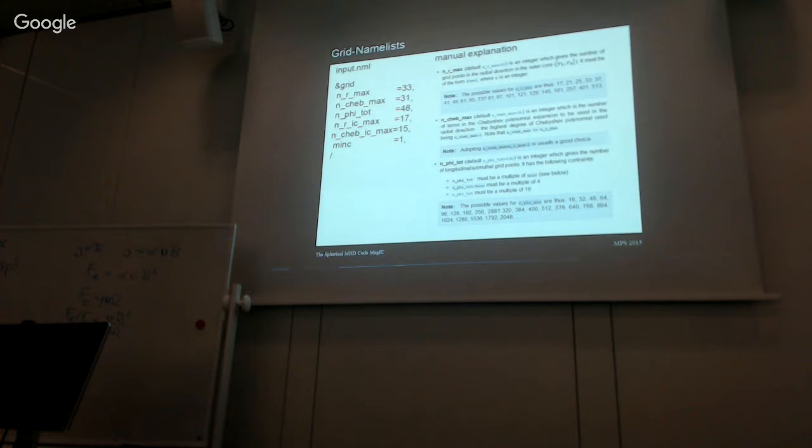So we can say that if your system is very turbulent and your motion happens on very small scales, then it doesn't matter whether I have just 1/2 or 1/4, because the small scale of your convection is so small compared to the 1/4 that it doesn't matter. But that's an assumption, which helps to save computational time. And for many problems, it seems to be a good representation. But certainly only if your Rayleigh number is so large that the length scales are indeed small.